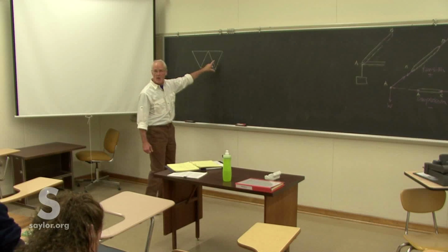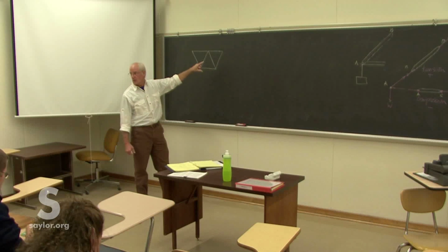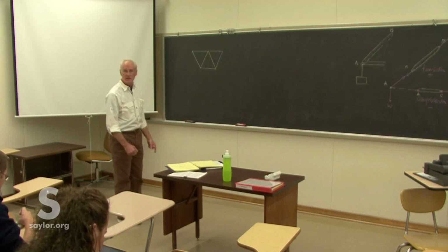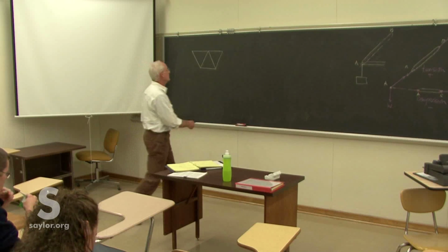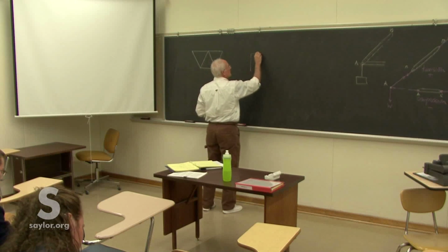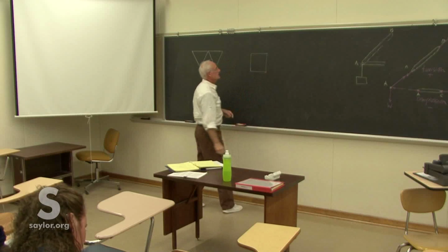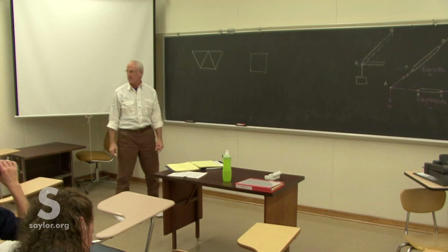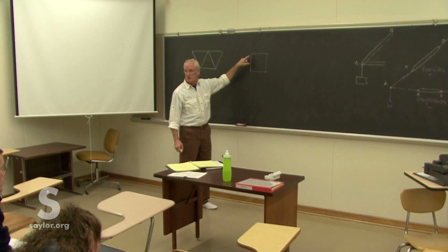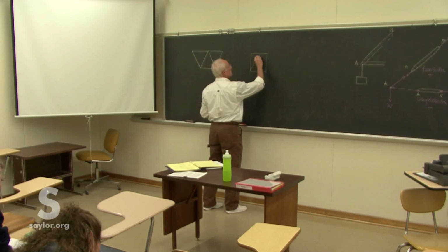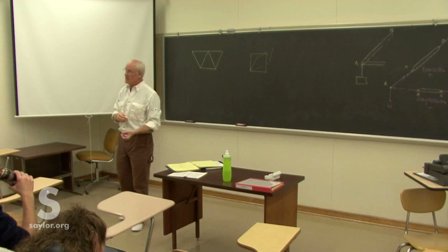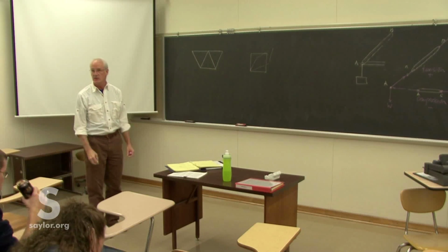Come spring, that's what we're going to look at, the possibility of these materials actually failing under these loads. We're going to assume now that whatever the materials, whether it's a wood truss or a steel truss, doesn't matter. There will not be material failure, but a triangle will not collapse. If we had part of a truss that looked like that, remember the joints are freely pinned and they can turn, which means that this could collapse and then the structure itself would fail even if there's no material failure.